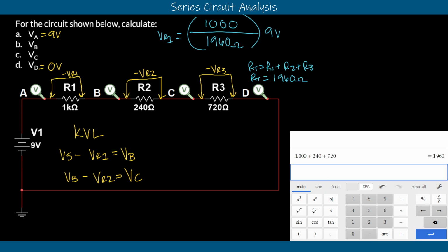Out and we'll say that we have 1,000 divided by 1,960. That's a ratio equation. And if we stop here and we look at this ratio, this number output, this 0.5, that has to be less than 1. If it's greater than 1, you've probably done something weird with your equation. You might want to go back and look at your 2 resistances and make sure you didn't accidentally flip the equation upside down, or make sure you've gotten your total resistance on the bottom there.